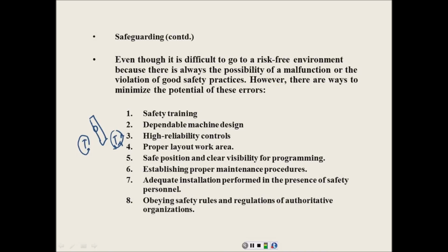These are your teach modes. All the other robots have one teach mode. You put it on teach, or you put it on manual; those are the same. We'll use the term teach. And then you've got another mode where you play the robot. I can't remember what it is, but it's up here. It's called play or auto mode. And then you've got another one up here for remote. So your robot has 4 modes of operation. Everybody else has 3: remote, play or auto, and teach.